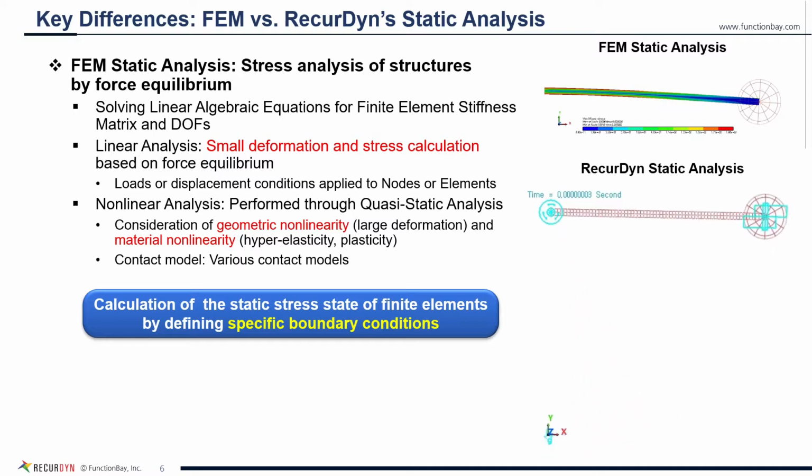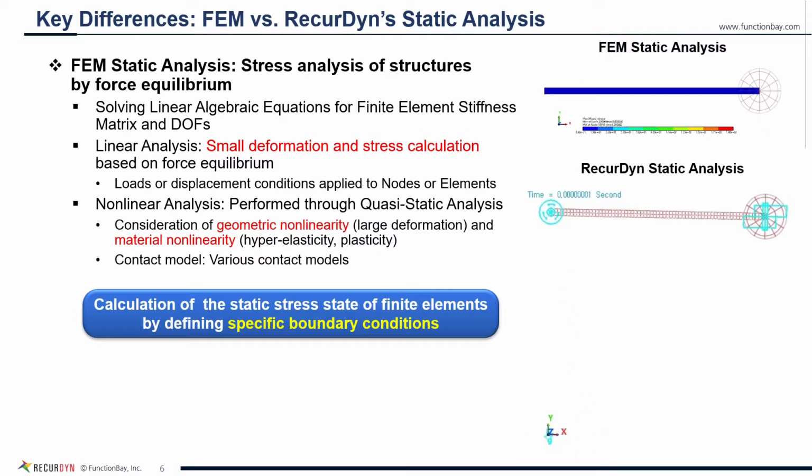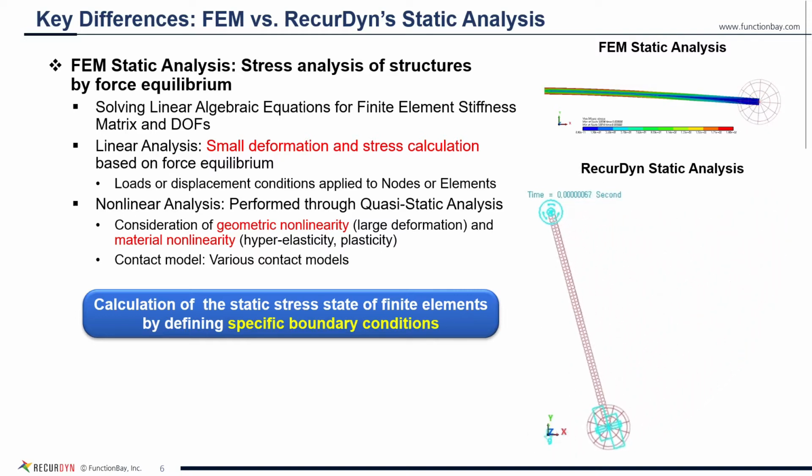Since FEM deals with large degrees of freedom, equations were solved for small deformations and force equilibrium conditions to reduce computational time. The quasi-static analysis method is used to implement geometric nonlinearity and material nonlinearity. In this process, specific and clear boundary conditions are essential.